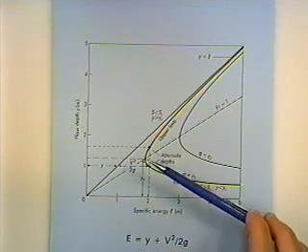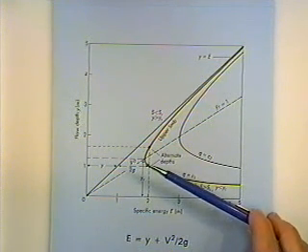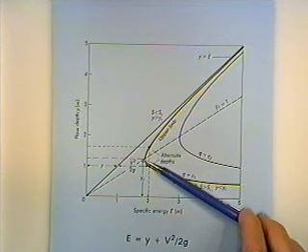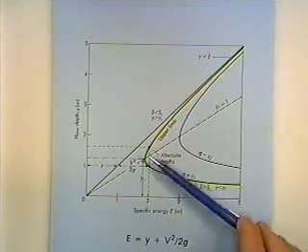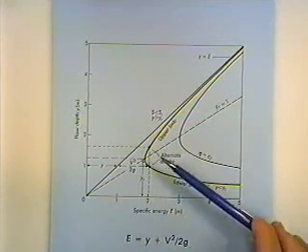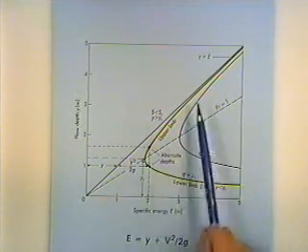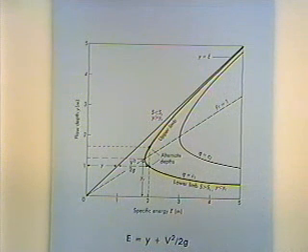By definition, critical flow is a condition at which specific energy is a minimum. So for these different depths, specific energy is a minimum right here at the critical depth. As we change slope or something else, the depth and velocity head will trade off, and we'll get a curve that looks like this.